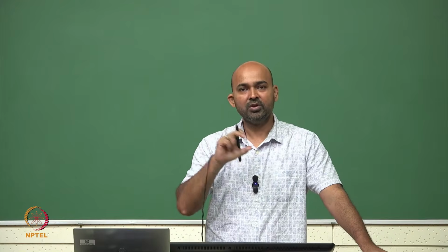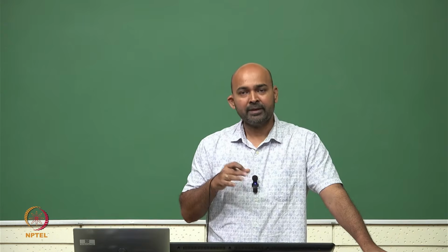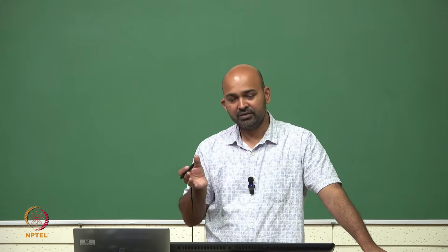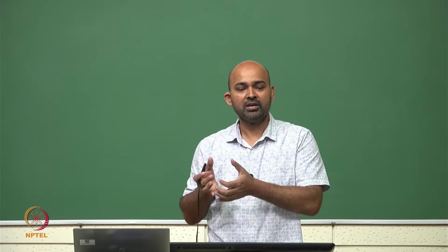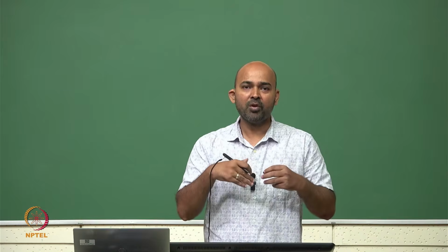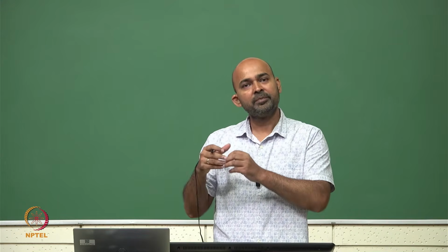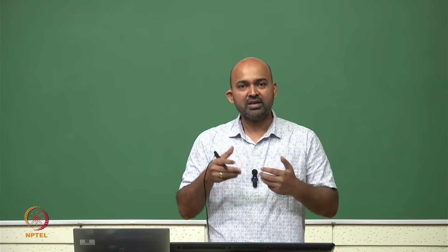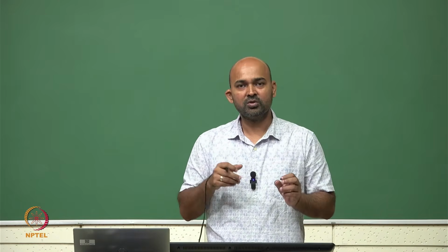If we apply a DC voltage across the capacitor, there is no current flowing in it. Similarly, the inductor is a short circuit for the DC operating point. So, when we perform a DC operating point analysis, all the capacitors in our circuit are going to be open circuited and all the inductors are going to be short circuited. SPICE does that in the simulation when it solves those matrices.